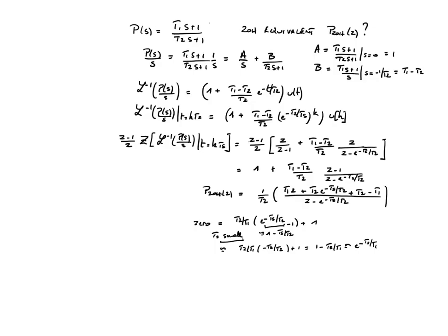We will do now an exercise where we have to find the ZOH equivalent discrete time description of a given transfer function. This is the type of exercise that you might have at the time of the exam, either with this method, the ZOH equivalence method, or any other method for a particular system. The transfer function that we're considering is that of a lead lag system. So here you have the lead time constant and here the lag time constant. And as we've said, we are looking for the ZOH equivalent description.